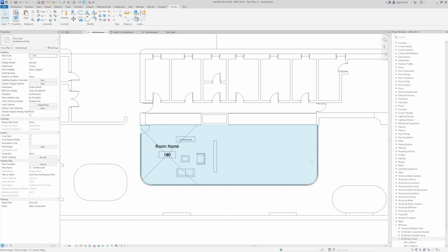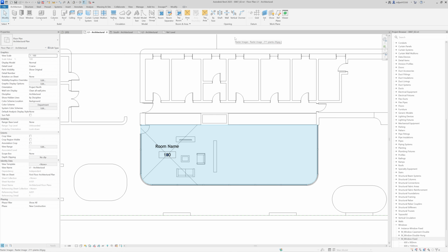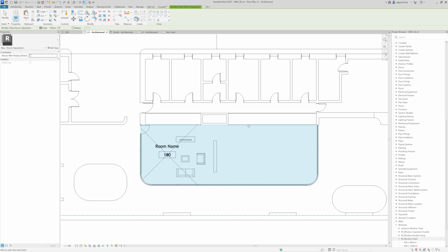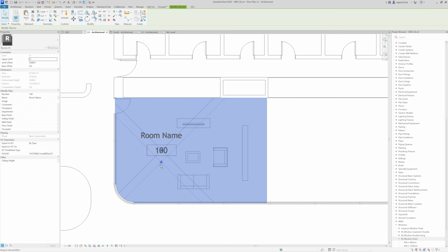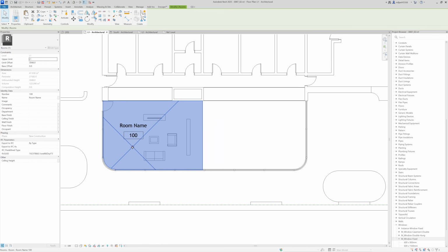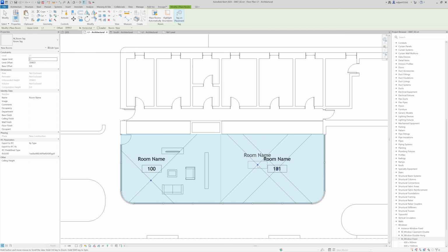And if you would like to separate the rooms, to split this one, you need to go to the architecture and then you have this room separator. So I can just, let's say, place it here, and then you see that we got this. So I can also keep the naming, and I can just now go create similar, and then I can place the other room, and then I can go and continue that way.